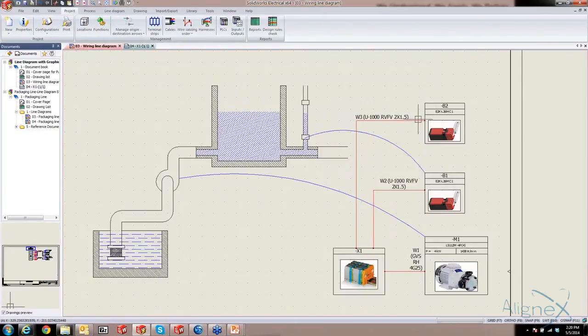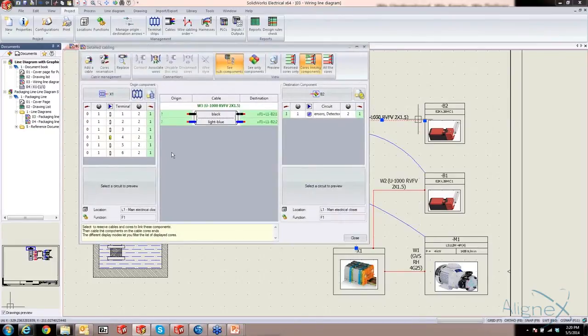So we need to do our detailed cabling for that particular limit switch. So I can just double click and go back in there. But you see I have a couple of question marks here. This side is already connected. It did what it needed to do to connect up to this from copying my original mark. But my second one, I need to add a couple of terminals.